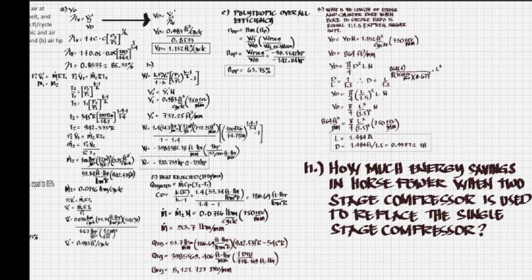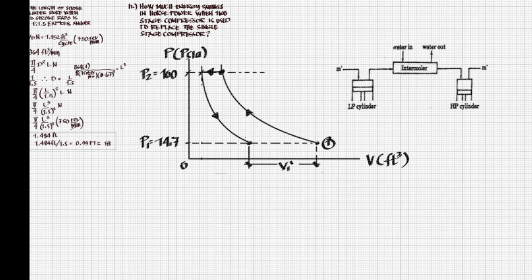Okay. Now, the next question is for letter H. How much energy savings in horsepower when a two-stage compressor is used to replace the single-stage compressor? Okay, so I bring down here the PV diagram and the schematic diagram of the two-stage compressor, a low stage cylinder and a high stage cylinder, when making a multi-stage compressor.